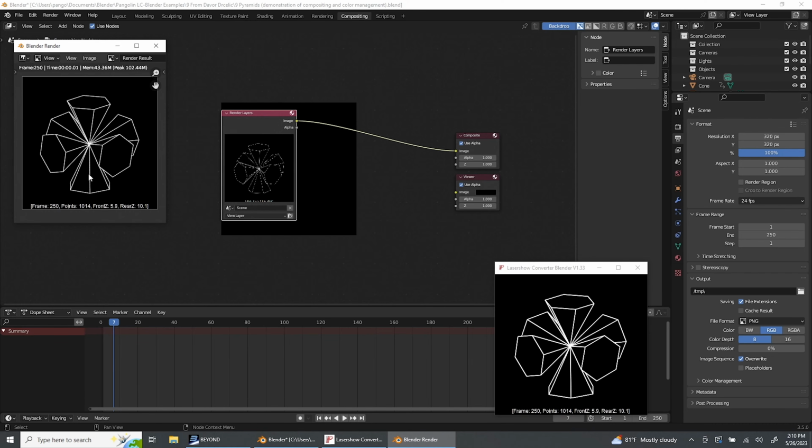You also may notice that this window here doesn't really keep up with the laser preview window. And that's because Blender refreshes this window at a different rate than real time. And so sometimes you may see weird blocks in here. You may see partial images. This has nothing to do with our plugin. It's just the way that Blender works. And so the point of this is just to show you, you may find things up there on the internet. You may receive things from customers that these are things to watch out for, because the professional Blender users use compositing and a whole lot of other things that may slow down the laser rendering option and do not really add anything to the laser.